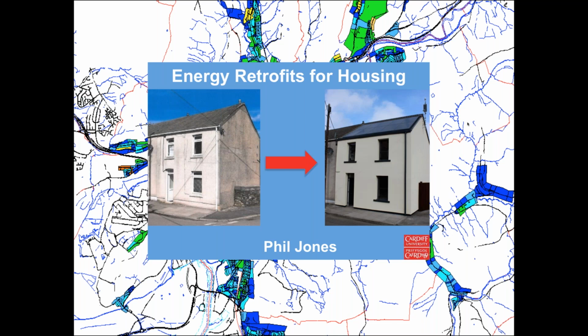Okay, you mentioned new build. Someone has asked, has there been any cost comparison study for retrofit against new build? I guess the question is really, do we demolish and build new, or do we retrofit? And we have done some studies in the past, and sometimes it's marginal, but it usually favors retrofit. And of course, there's quite a bit of embodied energy in our existing buildings. So it's not only the operating energy and the costs, we're losing a lot of embodied energy when we demolish a building. So usually it's more cost effective to retrofit than to build new.